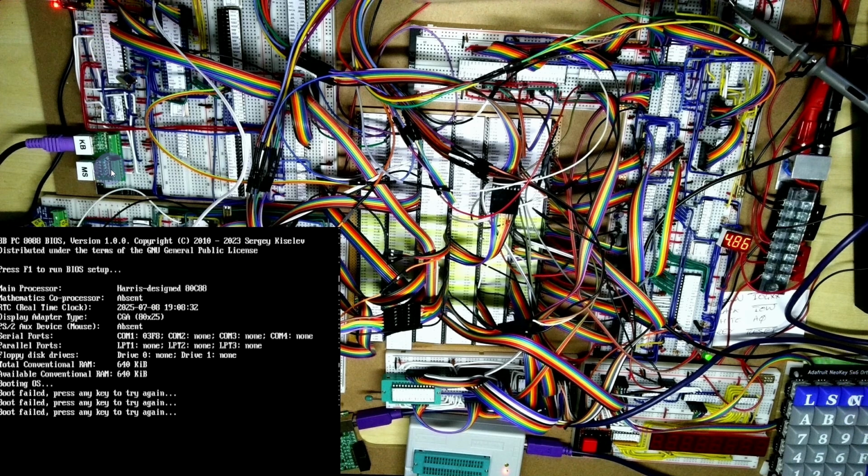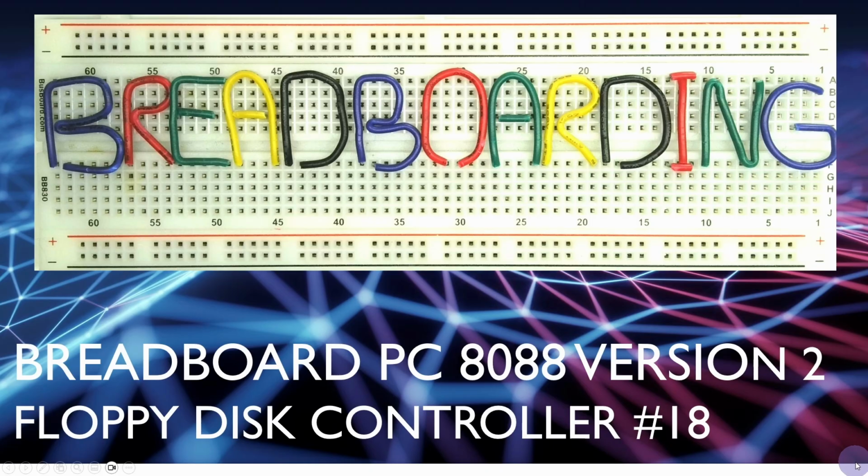Now the I/O board that we've already got working up here has the keyboard controller and also a serial controller already on it, and we're going to be setting up and then configuring the floppy disk controller and the floppy disk connector up here and trying to get that running. This is video 18 in the Breadboard PC 8088 version 2 series.